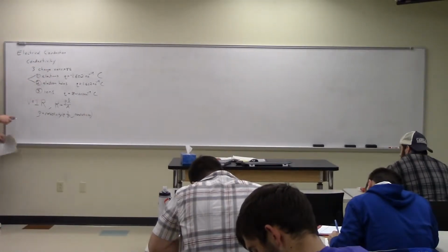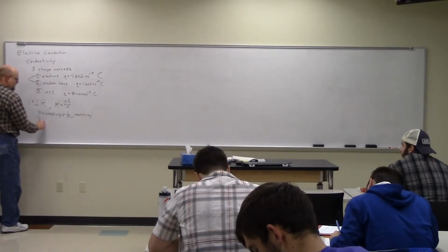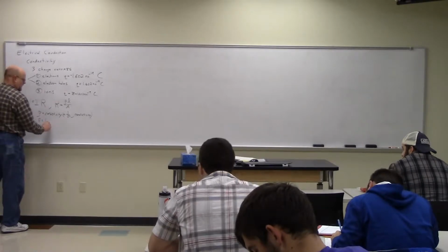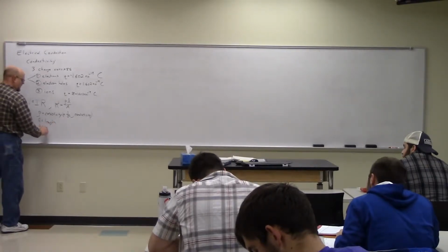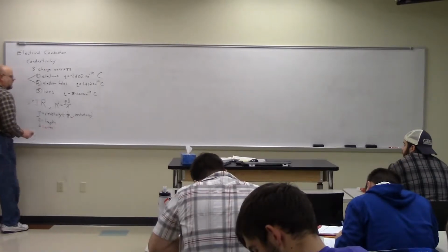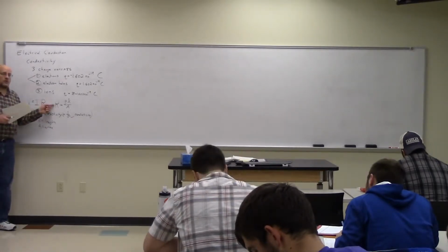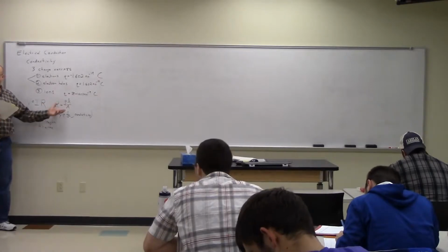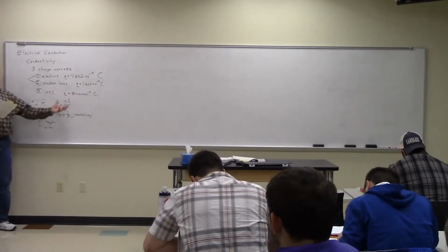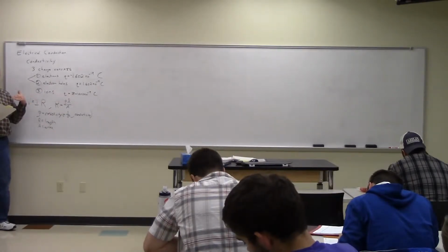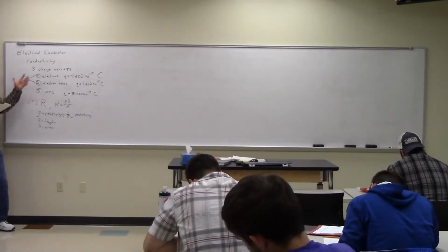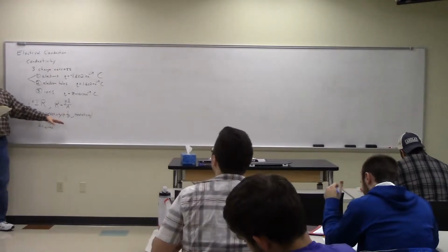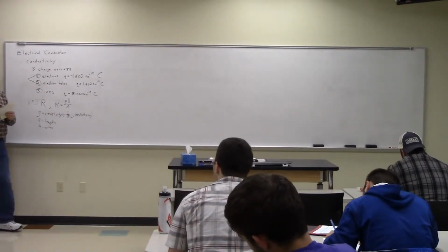Okay. L is the length of the conductor, and A is the cross-sectional area of the conductor. So this is why resistance is not a material property. Right? It depends on the geometry of the material. Resistivity is, on the other hand, a material property. But typically, in terms of what's actually going on, we define conductivity and then invert it to get resistivity.